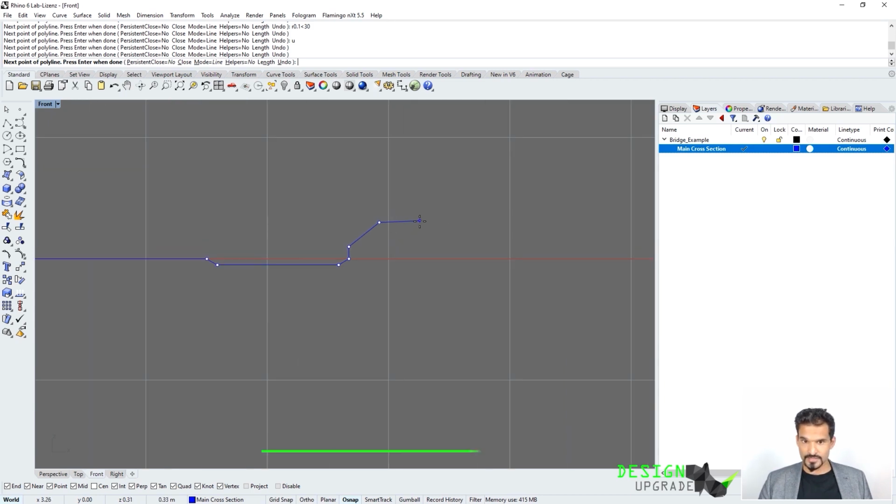The next thing is the zone or the area of where you can sit. We can just say 0.4, enter, shift button lock, enter. Now I want to have the same slope that I had here. So I say relative to my last point. And instead of always typing in 0 point something, you can just get rid of the 0 and just type in point and just say 2.5. Yeah, that's also something. Comma, and I want to go downwards. So I say minus 0.2.